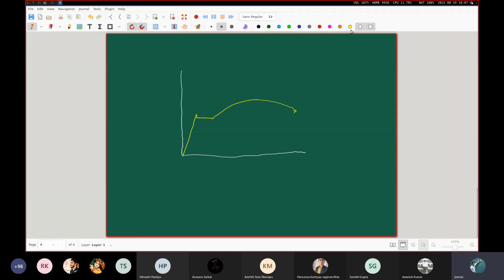All right, so this is our engineering stress versus the engineering strain diagram. I've just repeated what I had drawn in the previous class. Please note that this is not true or correct for any kind of material. Certainly not. If someone comes along and asks you to draw the engineering stress versus the engineering strain diagram, you have to first ask that person for what material. If he or she says draw it for low carbon steel, then draw this diagram. Otherwise, don't draw this. For example, and we will discuss this, the engineering stress versus the engineering strain diagram for something like aluminium is completely different from this. It has some commonalities, but overall it's quite different.